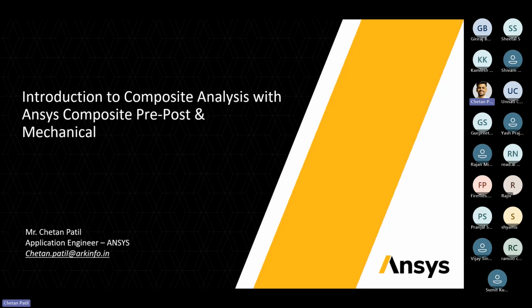And we'll see how Ansys Mechanical can be integrated with the Ansys ACP module. Previously, we had the Ansys ACP module where we could do the pre-processing part as well as the post-processing part. But with the latest version, we don't have the post-processing part. Even users who are more familiar with the previous versions, like before 2025, so 2024 or 2023, can still utilize the Ansys composite post module. I'll go with both, showing how we can do the post-processing in the Ansys ACP module as well as in Ansys Mechanical.